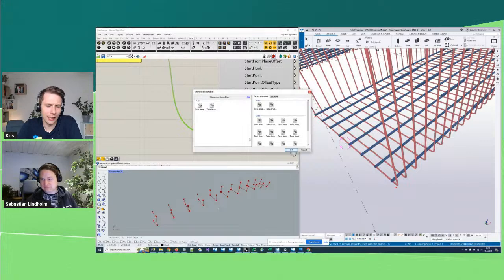I would just add that every time you work in a different Tekla version, if you would like to use this C# script afterwards, you need to update the references here with the same files, but from the previous version, right? Yeah, that's the downside. This will only work with 2023 because that's the reference that I added. But once you have created your script, you can go back here if you work in another Tekla version and just replace this with some other version, which you can browse or find here if you used it previously. So you can switch it, but that's the downside, like I said. So that's a good point.